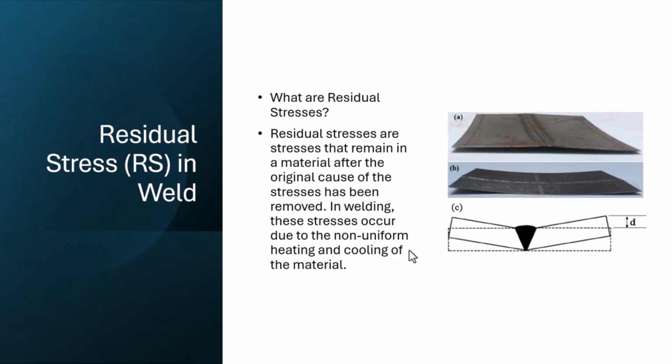Because if we look at this welded shape, you see here the material was clamped in the grip, for instance, and the material is melted and it needs to be cooled down slowly, and it wants to expand or contract, and these grips don't let it do that, and as a result it's going to distort and become a shape like this.